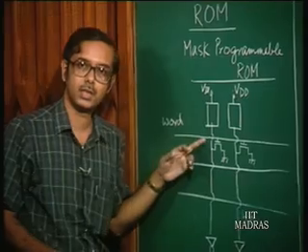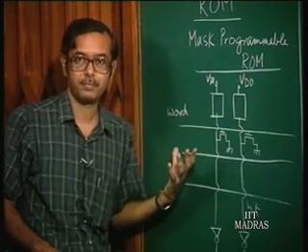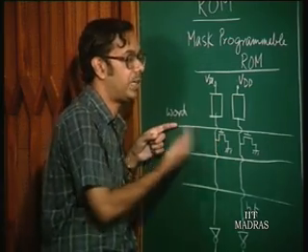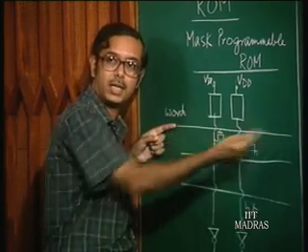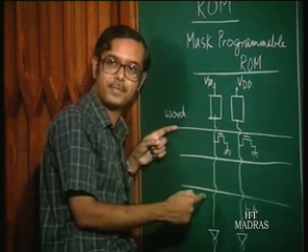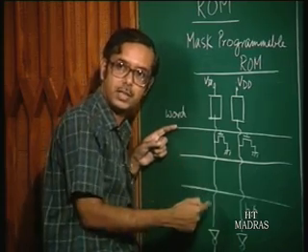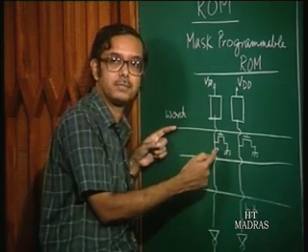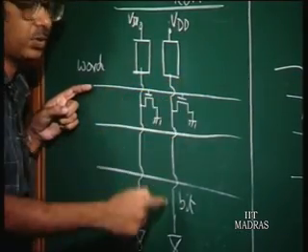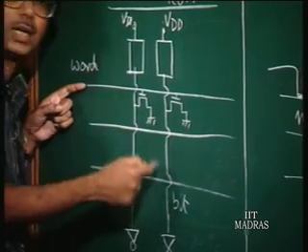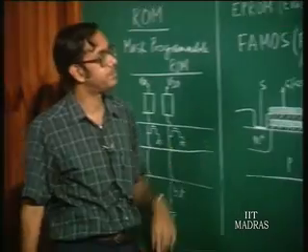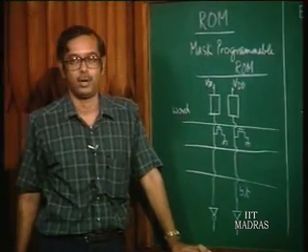the memory ourselves. Basically, if you want to program this transistor here, we have to apply 25 volts on the word line and 5 volts on this bit line. In which case this particular transistor will get programmed. And for all the other transistors, although you have 25 volts, you do not apply 5 volts drain voltage here, so they do not get programmed. So, this is how you can have an EPROM.